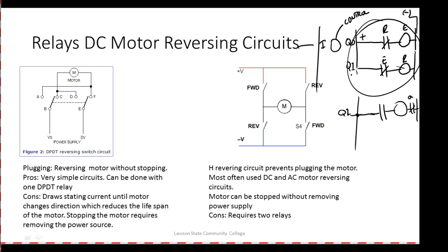How do we connect up to the PLC? You understand that? If I'm running sinking inputs, I know it's almost time for y'all to go now, that means my input devices, my sensors, whatever they are, have got to have a plus, right? Does that make sense?